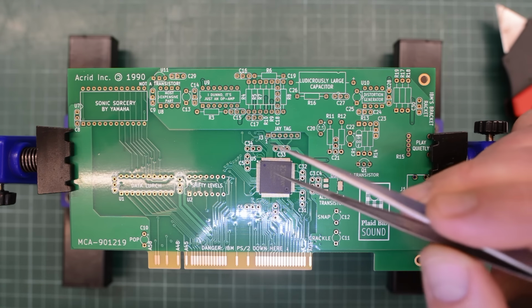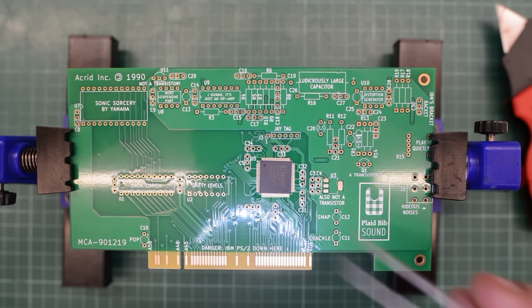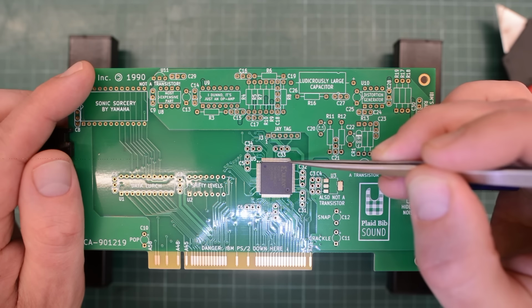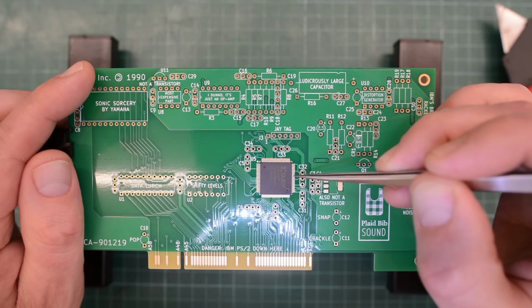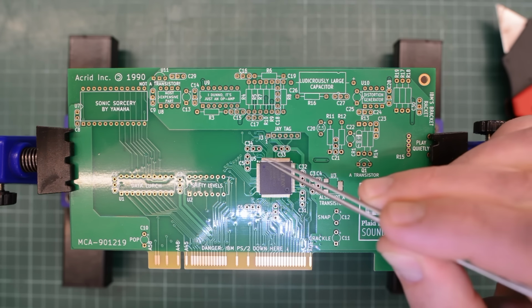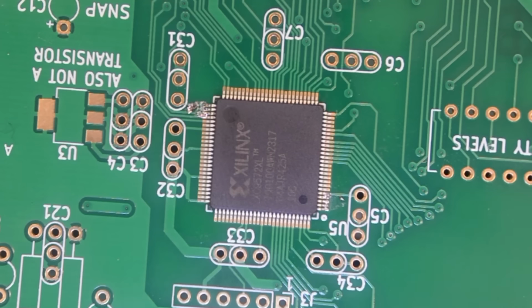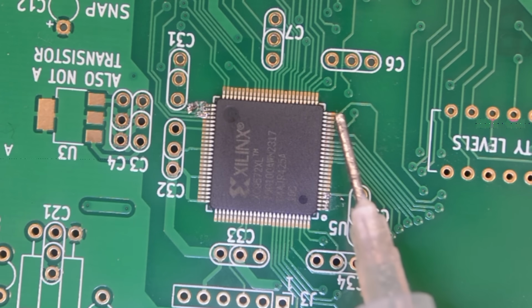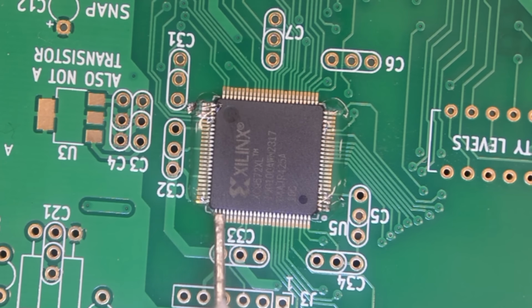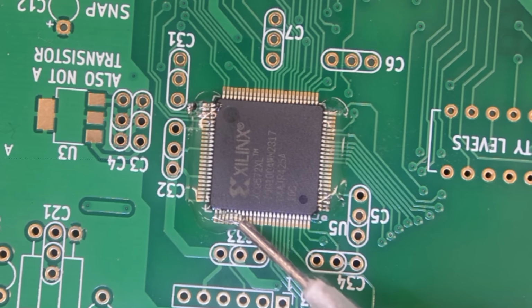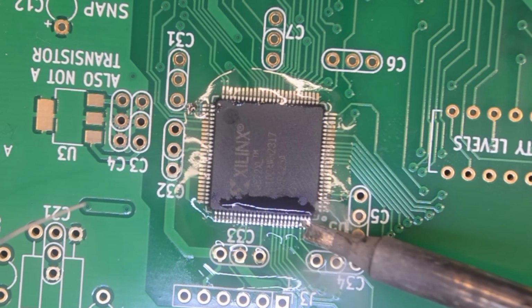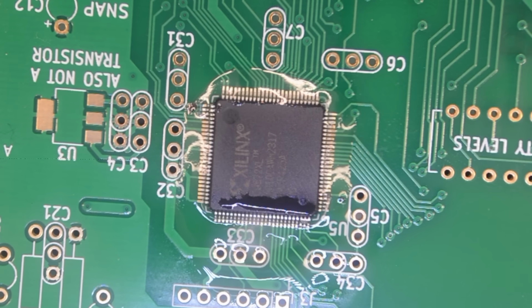The important thing here is to align the notch, of course. So, aligning a chip like this with the camera on top is pretty much impossible. So I'll take this off camera and solder two of the corners. Okay, a couple of the pads are soldered. So let's add some flux. I haven't soldered a chip with tiny legs like this in ages. So next I'm going to drag solder and ignore the bridges for now.